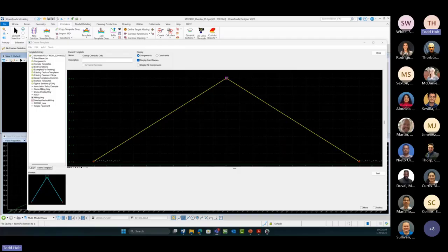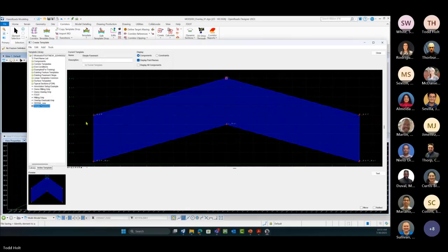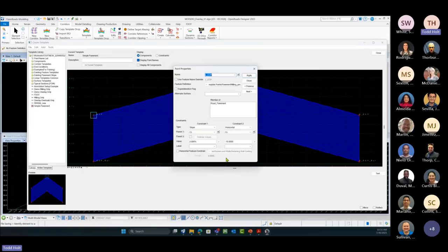All right. Well, I do have time. I think everybody is back. So let's go ahead and take a look at our templates again. I'm going to look at this simple pavement. All I did to set that up was a simple pavement to our left edge of pavement at a 10-foot or 12-foot, so we're just doing a saw cut line to mimic that.